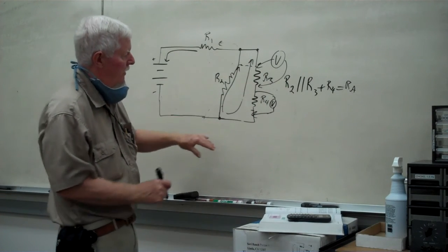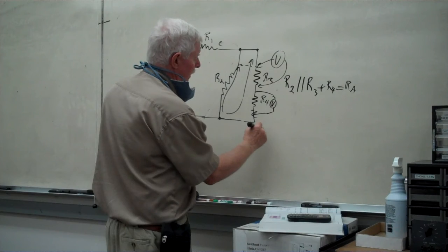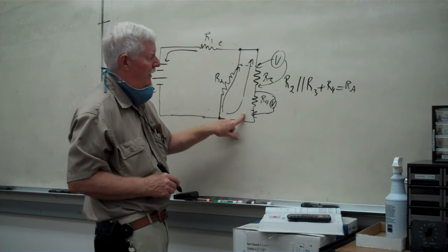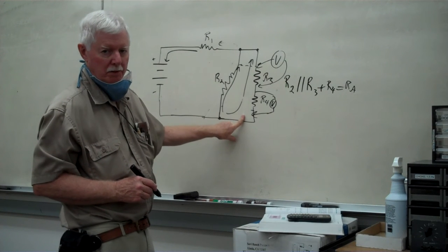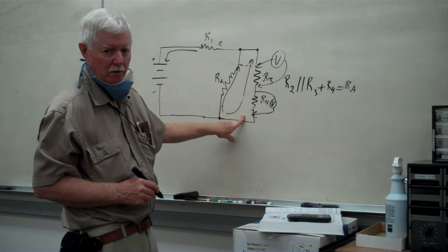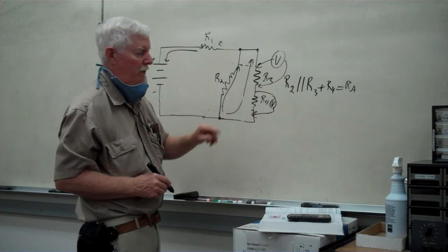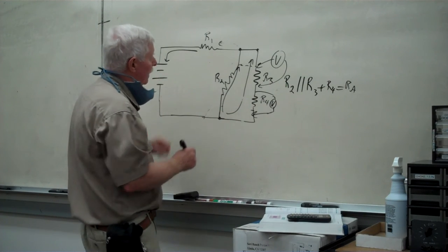We would find out that if we added those two voltages, that we would actually come up with the voltage that's out across the entire network. And it goes back to our original premise that voltage across the parallel system is essentially the same for every one of the branches.